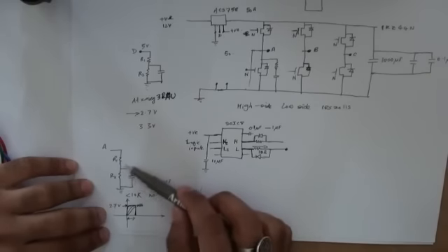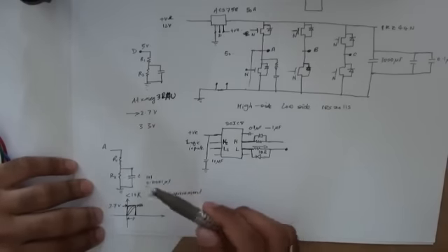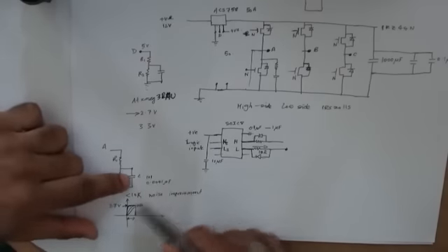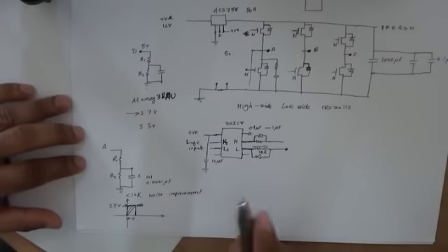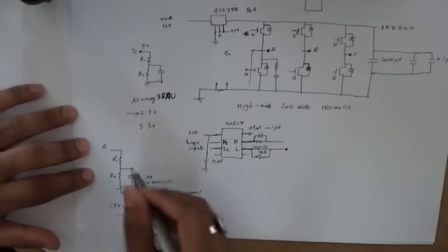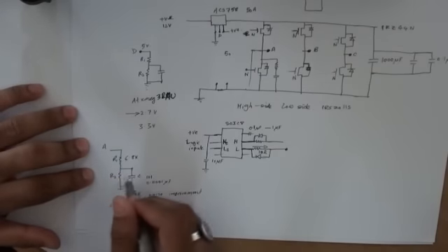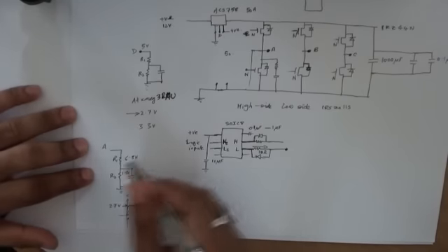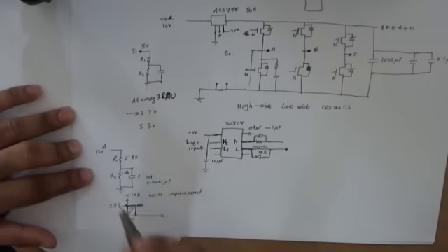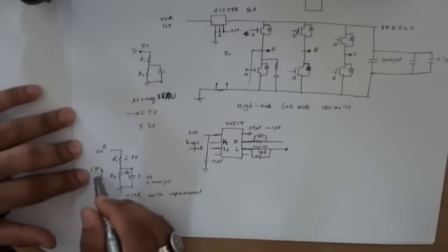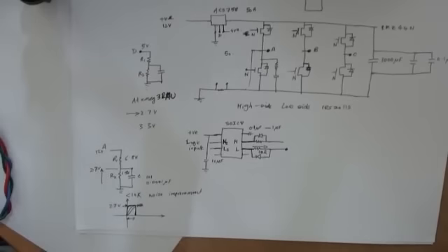So you want to use less than 10k as your resistor, and your capacitance to be reasonably small, but at the same time giving you filtering capability. In my situation, I used a resistor of 6.8k and 1.8k. That gives you the desired ratio between a maximum of 12 volt there and a maximum of 2.7ish volt up to there, and that's adequate for your microcontroller.